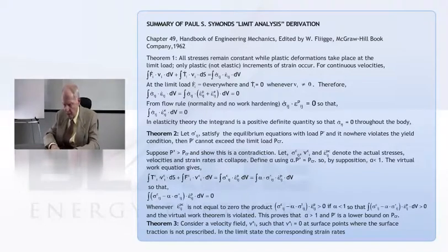And if you remember, if you have the combination of the Levy-Mises stress-strain equations, the Mises condition, and no work hardening, you take those three things and put them together, then this term sigma ij dot times epsilon plastic ij dot equals 0.